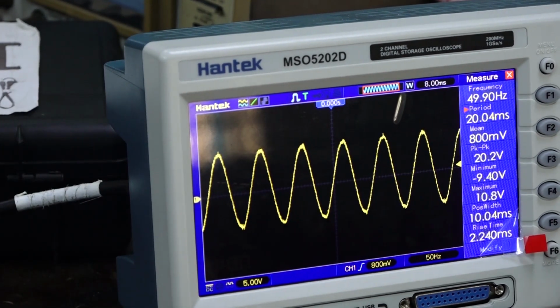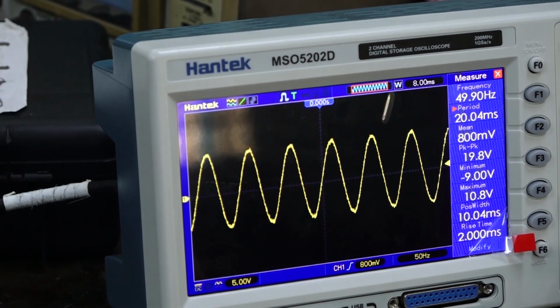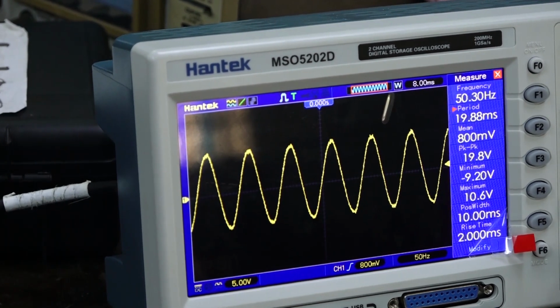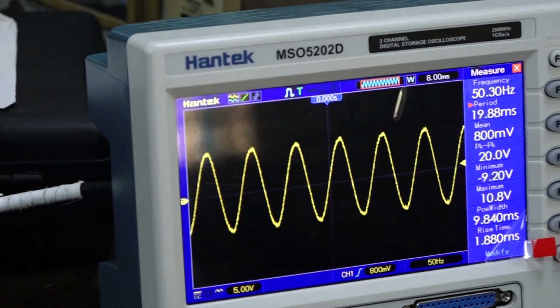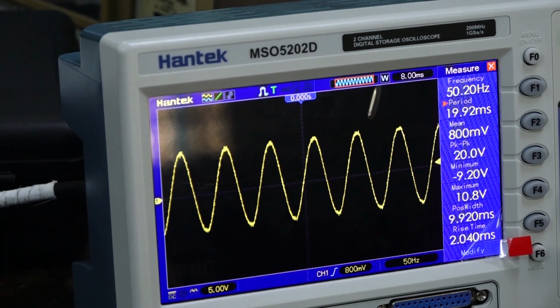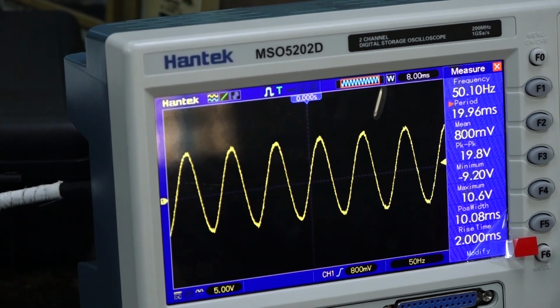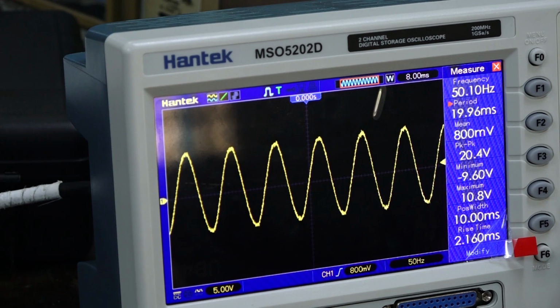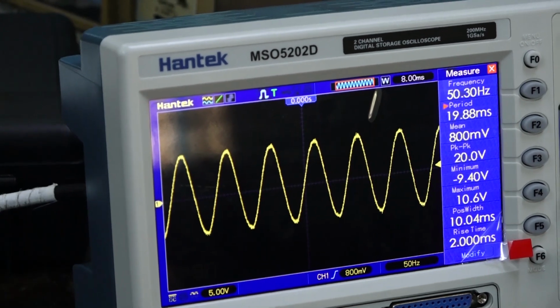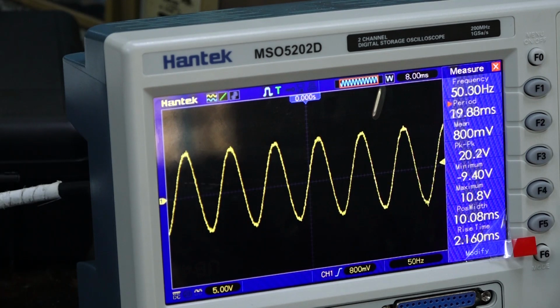What is the average? If it's varied, what is the average? Write what you see. Some of you write 50, others write 80. But remember, that 50 is not measured by the frequency meter of the digital multimeter. That 50 or 49 point something is measured using the oscilloscope. Sometimes you might be asked to measure the frequency of the signal using the oscilloscope, so don't say the oscilloscope does not have a frequency meter. Who told you? Simply say that you don't know the oscilloscope.